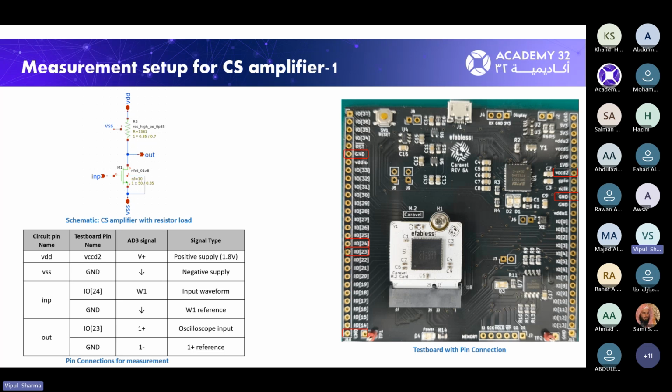That information is available in that table, and that is decided by how a designer, whenever he has integrated his design in a die area, used which pins or ports to make those connections. That is basically the responsibility of the IC designer, that he should pass on this information to the test engineer.